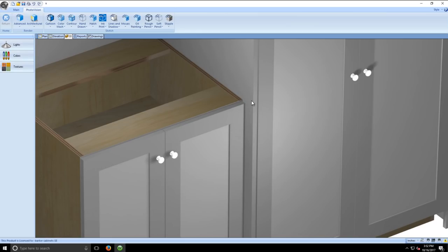It doesn't look professional, in my opinion. I know they all do that, and a lot of companies will fight tooth and nail to do a 24-inch deep pantry because they don't want to stock the 26-inch cabinet depths. And the real reason for that is our sheets come in 4 foot by 8 foot, so you can get two 24-inch rips out of one 4 foot wide sheet of plywood. So all of ours are custom. We do a ton of these, so the idea is that they get mixed into the sheets just fine. We don't have that much fall off. But that's the idea. It looks better.